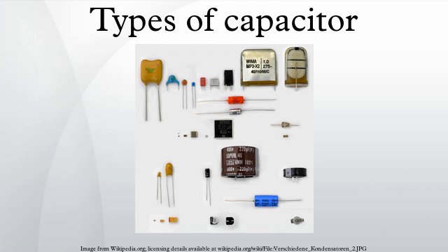In wet electrolytic capacitors, higher temperatures force the evaporation of electrolytes, shortening the lifetime of the capacitors. In film capacitors, higher temperatures may shrink the plastic film, changing the capacitor's properties. Pulse currents, especially in metallized film capacitors, heat the contact areas between end spray and metallized electrodes. This may reduce the contact to the electrodes, heightening the dissipation factor. For safe operation, the maximal temperature generated by any AC current flow through the capacitor is a limiting factor, which in turn limits AC load, ripple current, pulse load, etc.